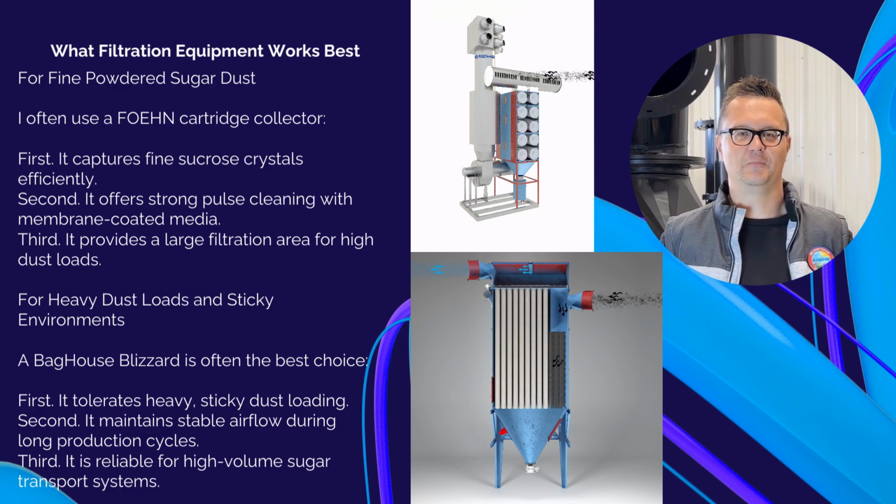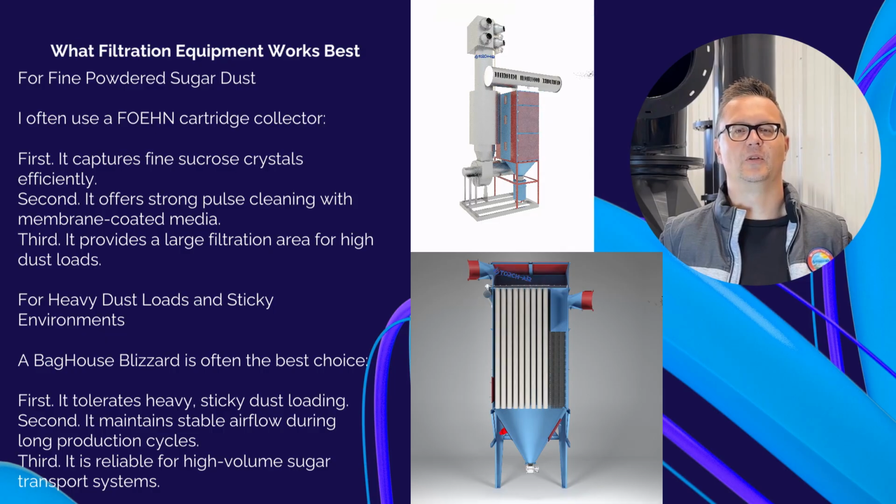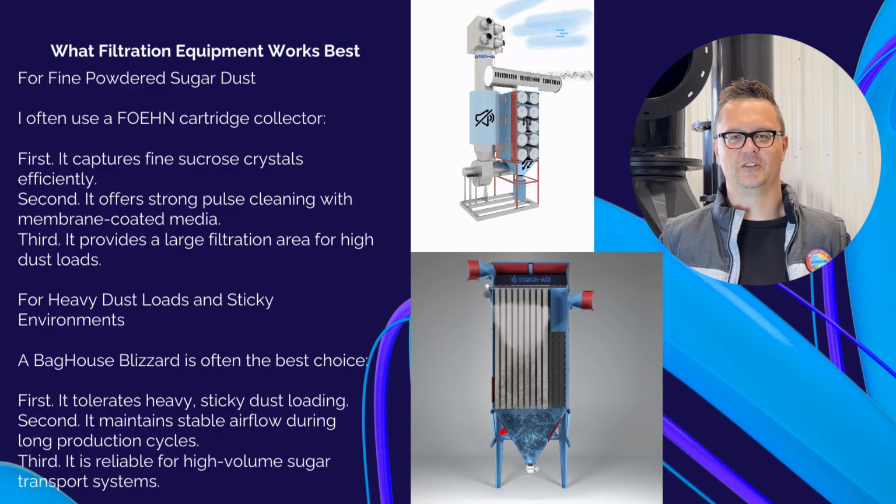Explosion protection. Because sugar dust is fully combustible, I always include, first, explosion vents on the collector. Second, isolation valves in ductwork. Third, anti-static filter media. Fourth, grounding and bonding across all equipment. Fifth, optional spark detection in milling lines. Safety must come first in every sugar handling facility.